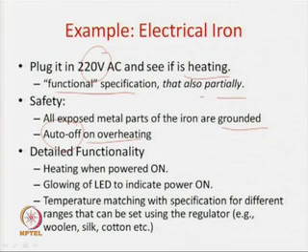Following that, if I go to a bit more sophisticated electrical iron, which are available nowadays, you can see that it has an LED. So, when you put the electrical iron on, when the heating is going on, an LED glows, and whenever some threshold temperature is reached, the thermostat detects that the threshold has been reached. So, it switches off the heating of the electrical iron for some time, and then the LED becomes off, and it goes on in this round.